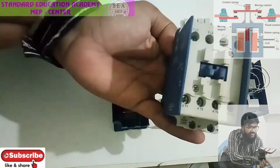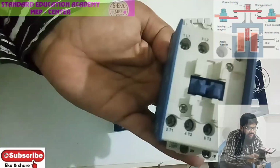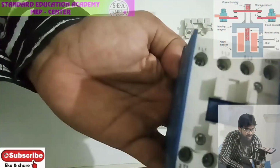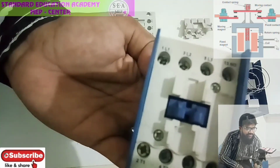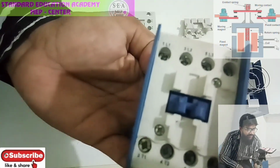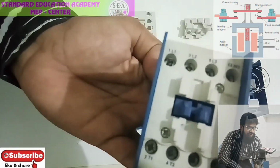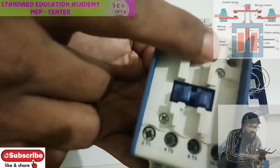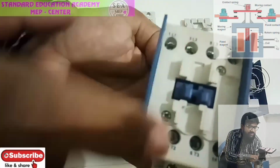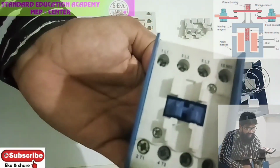And here you can check out 13NO, 14NO. It is actually an auxiliary contact, we name it as NO, normally open, which will be used for the electrical circuits wherever required. So as of now, L1, L2, L3 are 3 input supplies, and T1, T2, T3 are 3 output supplies.